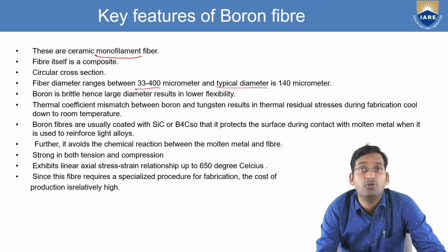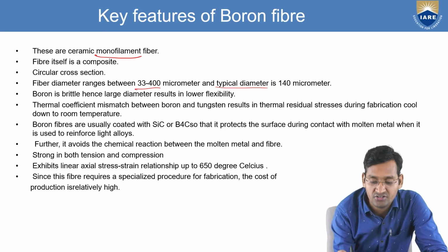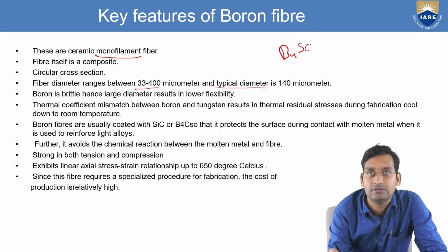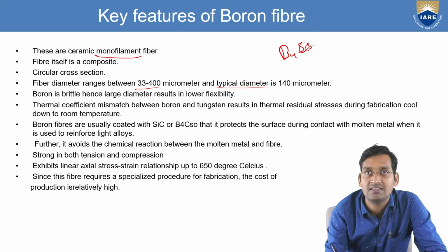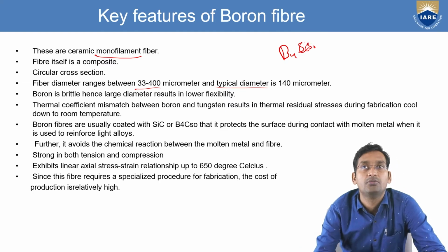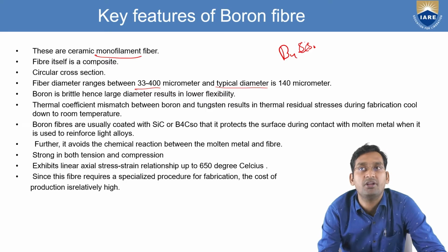Boron fibers are usually coated with SiC, silicon carbide, or B4C. It protects the surface during contact with molten metal when it is used to reinforce light alloy.